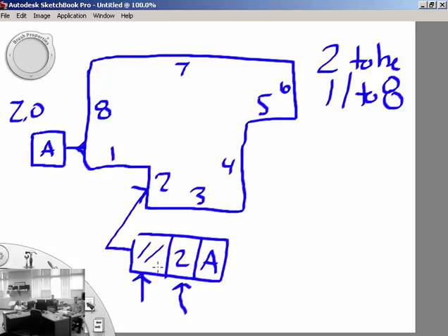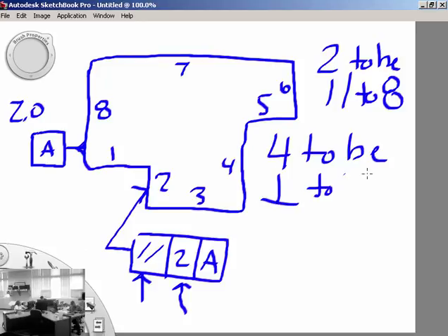So awesome. Now let's turn around and do a little bit different one. I want surface 4 to be perpendicular to 7. So go ahead and add that to your sketch now. So walk me through. What's my first step I need to do to make this happen? I need to establish which one's the datum. So which one is the datum?